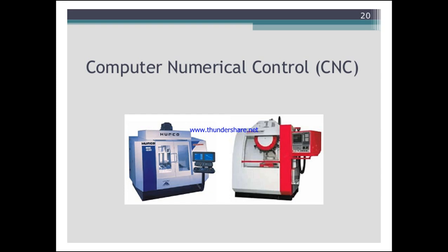But when we talk about numerical control by using tapes or by using direct numerical control, the program cannot be stored, it will be erased. When the machine gets switched off, automatically the codes will erase. So that was a problem we were having. So that is eliminated by using this CNC. So the contents in ROM are retained even when the controller is turned off.